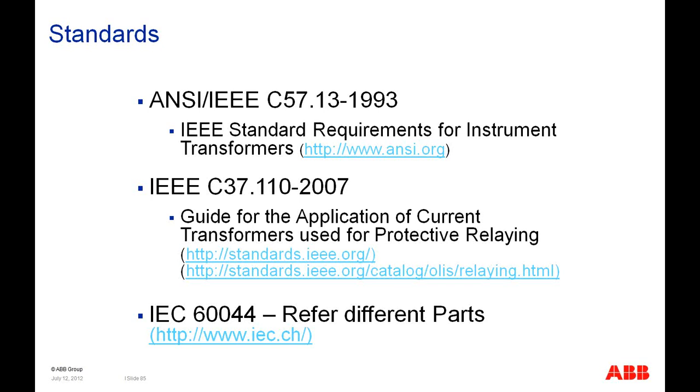The CT saturation calculator is actually on our PSRC website, which happens to be www.pes-psrc.org. And under reports, you'll find that CT calculator in there. And then there's IEC 60044, which refers to different parts of the current transformers and voltage transformers.